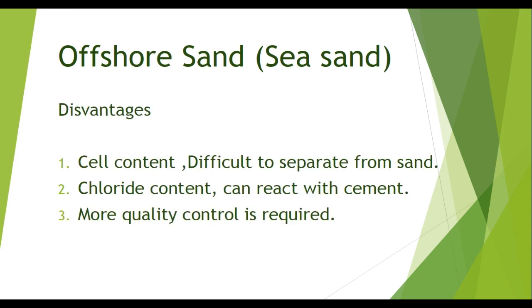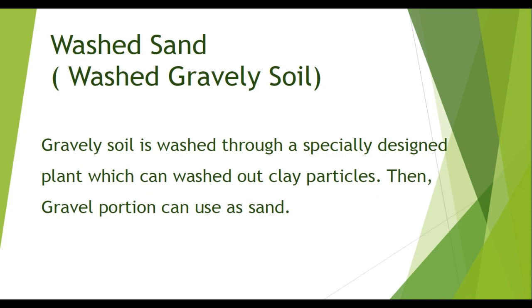First one is salt content, which is difficult to separate from sand, because most of the sea sand has salt content, and there's chloride content which can corrode the reinforcement in the concrete and affect the cement of the concrete. And more quality control is required because we have to test chloride content, sulfate content, and shell content, and therefore advanced lab equipment is required. Those are the disadvantages.